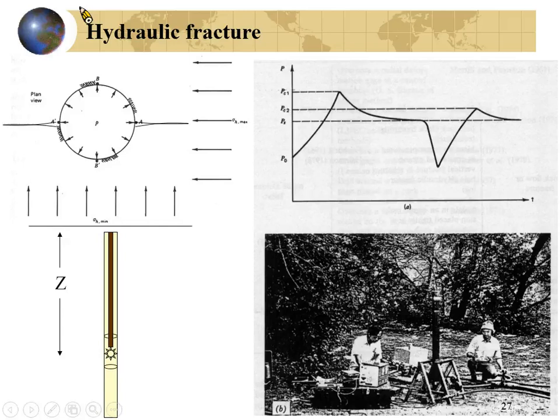Then the pressure drops down rapidly, to relatively a little bit lower than the hydrostatic pressure, because you have new fractures. Relatively, it will be similar. Then you open the pump again to inject pressure into that segment. The pressure develops again to a peak value, then starts to decrease.